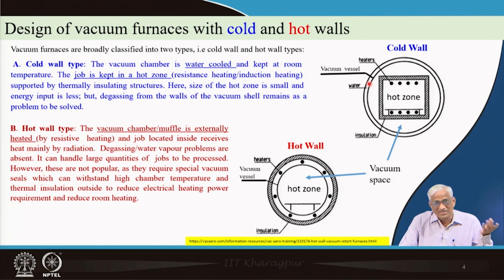So, all the gaskets etc., they will not be in trouble, they will not degas, they will not suddenly melt and all. But the disadvantage is the chamber is not properly degassed. So, you have to initially purge it properly, run the air blast for a longer time, all those issues as a part of the design or scheduling have to be done accordingly.